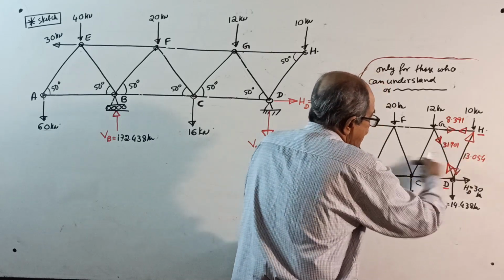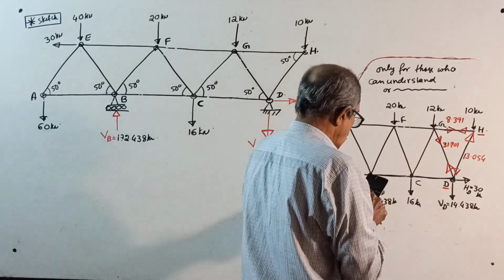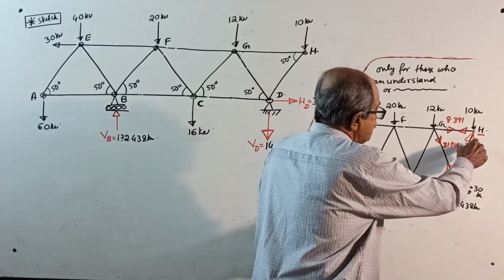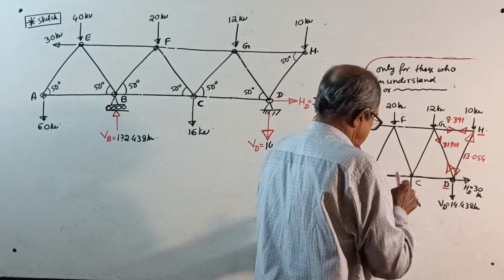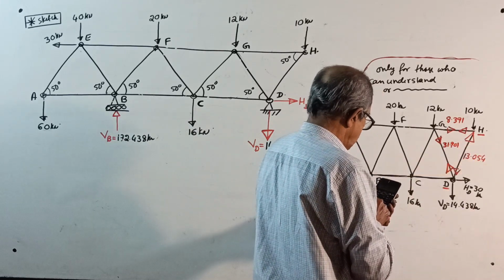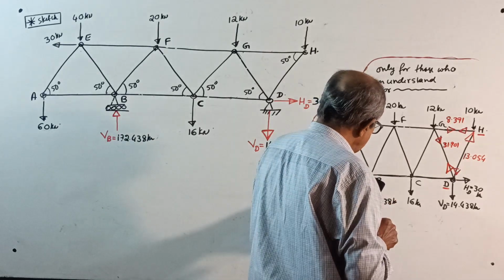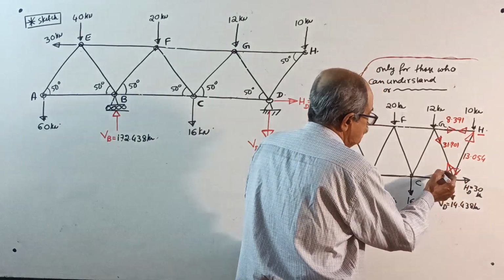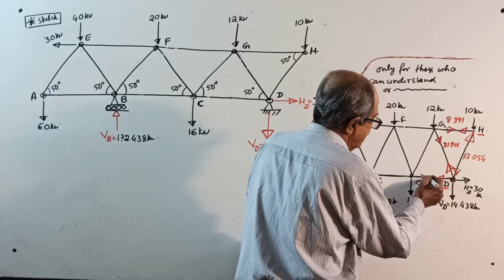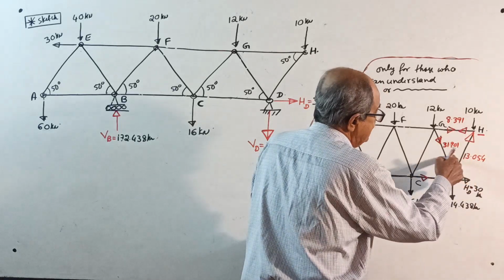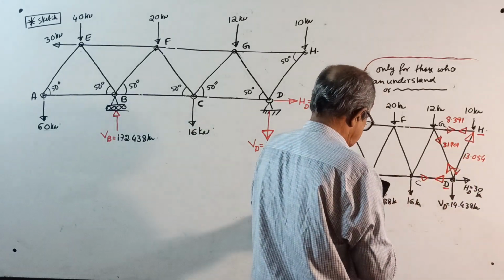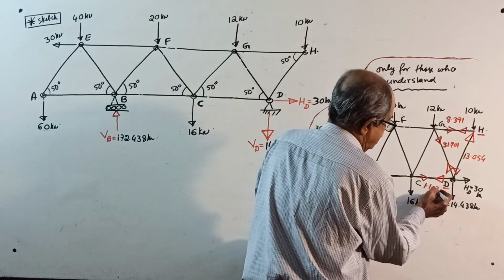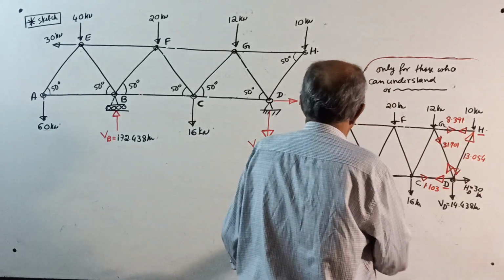Its horizontal component is left side into cos 50, which will be 20 point something. Even this horizontal component is like this, plus 13.054 into cos 50. Together it comes to 28.89 something. There is a 30 force that side. To balance, I require one more force like this here, which is the difference of this component and 30. 1.103 is that answer.